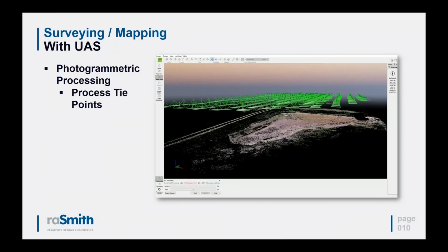So this next slide just shows that structure from motion photogrammetric process taking place. In this particular case, you can see the software start to pull together where all these images are located, and it uses metadata that was stamped on the photos to help initially position these pictures where they were actually taken in flight. And then it goes through on a picture-by-picture basis, and it actually compares one pixel across all those pictures, pixel by pixel, and then fine-tunes that adjustment, and using this process of triangulation creates all these tie points.